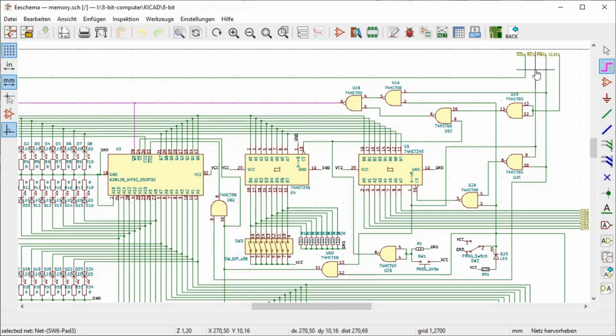On the other hand, if memory read is requested, the memory enable line gets low, and that means that the bus transceiver is set into direction from RAM chip to the data bus. And also, since a low input on an AND gate always sets the output low, this line gets low, and so the output enable is set active. This is active low, and the chip select 1 is activated because this is another AND gate where a 1 and 0 input lead to a 0 output, and so the chip select 1 is also activated.